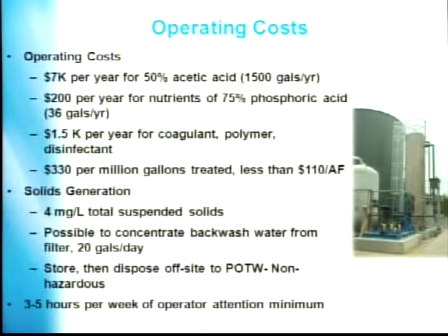And then you have some solids generation, I'd say about 4 milligrams per liter for this specific application, treating 50 gallons per minute. And you have some backwash water. That can be disposed right to the POTW, either trucked off or discharged if you're local to a POTW. And then the operator attention, I'd say, is about 3 to 5 hours per week minimum. That doesn't include sampling and analytical. If that's required, there's going to be additional time associated with that as well.